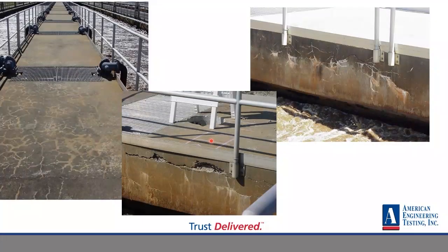Again, here's some dams. Dams are obviously pretty susceptible to this if they use reactive aggregates. There you've got that alkalizing the concrete, and they have a lot of moisture available. Again, you can see that alkali-silica gel in this upper right photograph starting to pour out of those microcracks, those fractures.